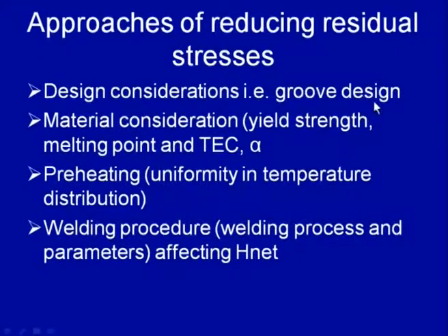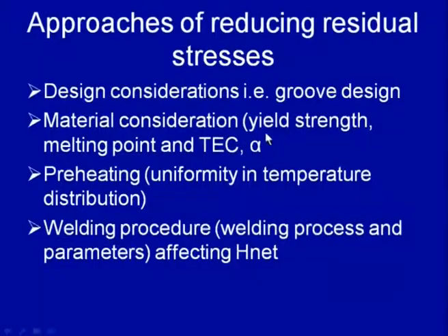Further, the design considerations are also used for reducing the residual stress magnitude, that is the groove design. The design of the groove should be such that it reduces the volume of the weld metal to be deposited, because a greater volume of weld metal to be deposited increases the residual stress magnitude that is developed after the welding. Material considerations like the low yield strength metal having the lower melting point and the lower thermal coefficient will help in reducing the residual stress magnitude.